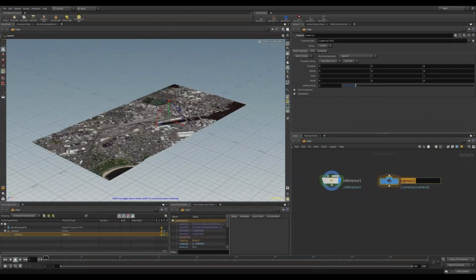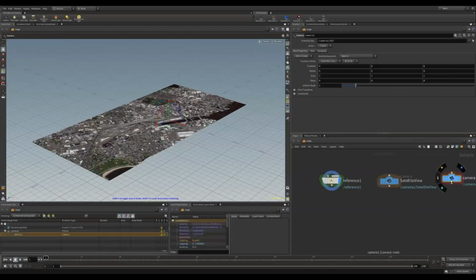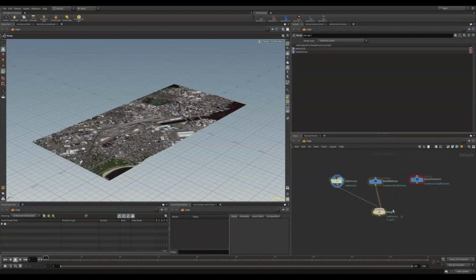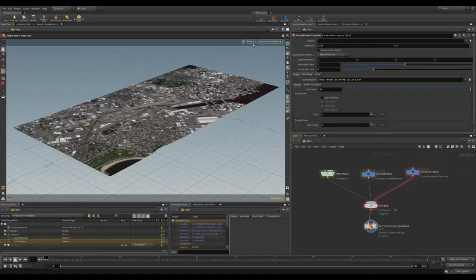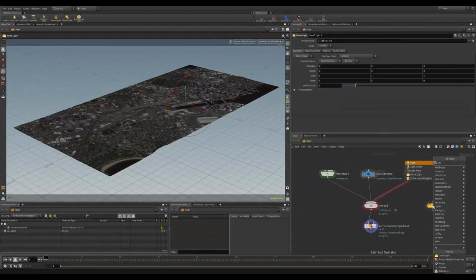In case you're wondering how Houdini found the satellite texture, we make use of the built-in USD Preview Surface material definition. I will explain this in detail later after we finish creating the streets and building models within CityEngine. Finally, we put down a merge node and pipe it through a Karma render settings node as well, so we are ready to render the scene at the end. Now that we have some scene content, we can also add some lights and just quickly see if Karma, the USD specialist renderer, is able to correctly light everything.